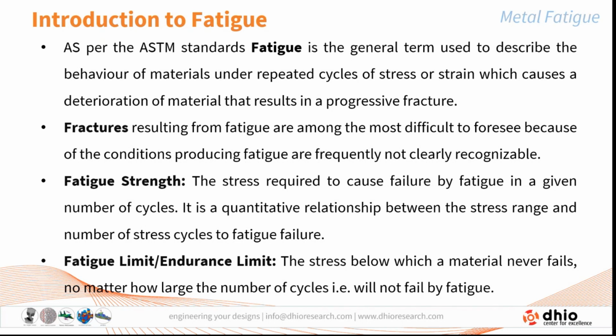Then we define the fatigue strength. It is the stress required to cause failure by fatigue in a given number of cycles. At what level of stress induced the member is going to fail, and for how many cycles. The stress induced for that particular number of cycles is what is called the fatigue strength of the material. It is a quantitative relation between the stress range and the number of cycles to fatigue failure.